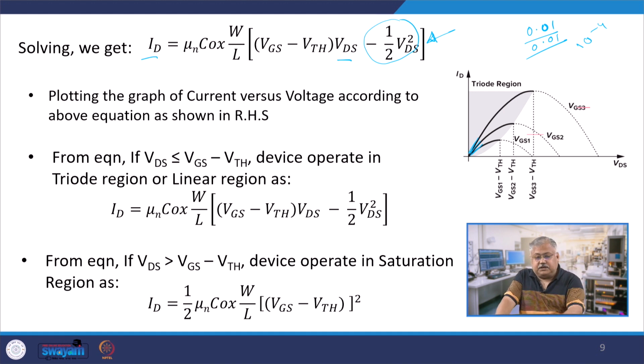If you just take this expression, then as you start to make your voltage go higher and higher, the Vds terms become more dominant, and therefore, with a negative sign, you would expect to see a decrease. And since this second term is a parabolic term, you will see that beyond a particular point of Vds it will start going down, and that is what is shown here. At any fixed value, do not worry what that value is at this stage, but at some value it might happen that this will exceed this value, and as a result the current will go down, not expected.